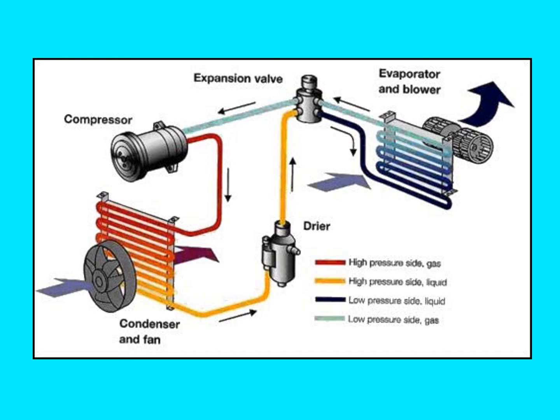So this is just showing another layout of the expansion valve. The expansion valve shown in this one is more of an H valve configuration, or they may refer to it as a TXV block valve. And it makes a very convenient connection point for the evaporator connection to the high side and low side lines. So again, they refer to this as an H valve. In most manufacturers, that's what they're using now instead of a capillary tube TXV system.